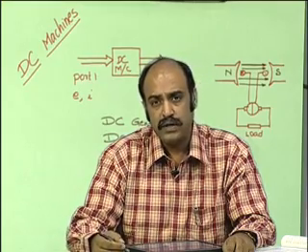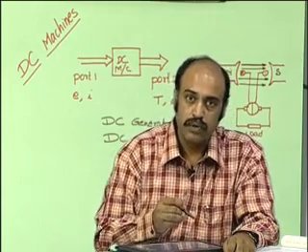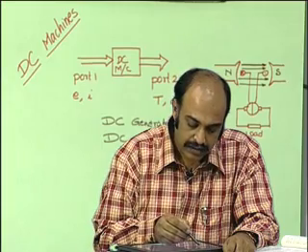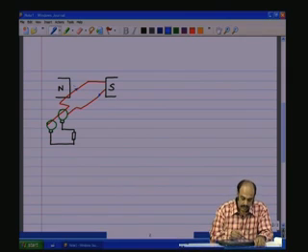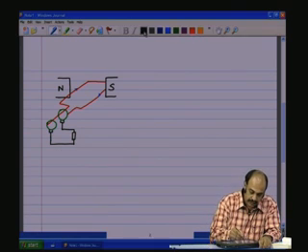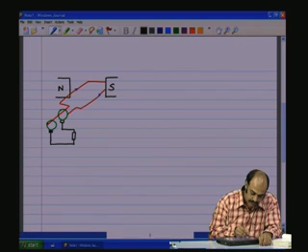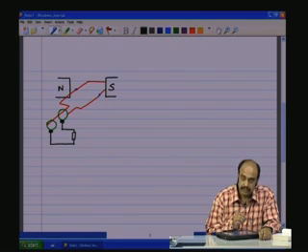And just to have a quick review, we saw that in the last class, if we have a north pole and a south pole and a coil as shown here in red, the conductors near the north and the south pole will have the current directions out of phase, and these currents are going to be flowing through the external circuit through these brushes in black. Now, these brushes are in spring contact with the ring to which the coil is soldered. One end of the coil is soldered to one ring, the other end of the coil is soldered to another ring, and that is in contact with this brush.